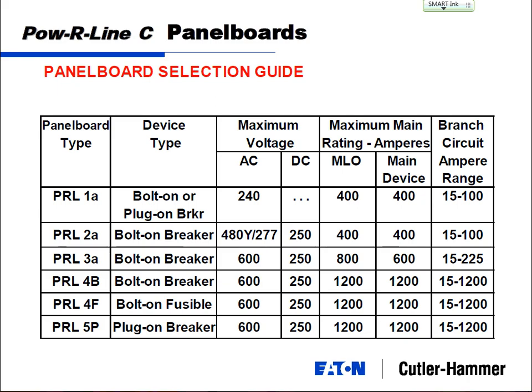In a short circuit condition, I've got my same 20 amp breaker, and now I'm taking two wires at my receptacle and banging them together, creating a ground condition, to where all of a sudden instead of 20 amps flowing through that breaker, I've short circuited to where I've got 200 amps or 2,000 amps going through that circuit breaker. In that case, that breaker is going to trip off as quickly as possible. It's not looking at time. It's going to see I've got way too much current and trip off quick.